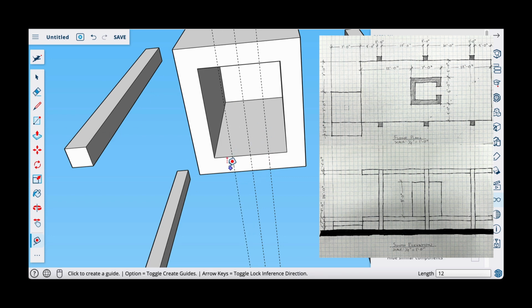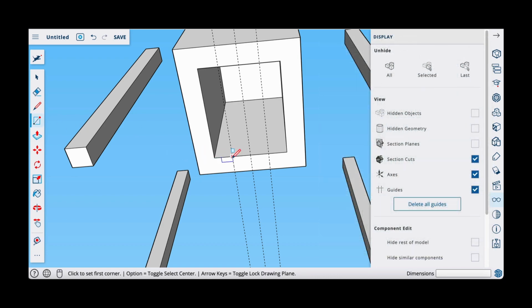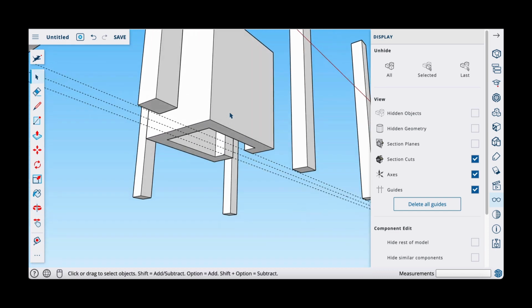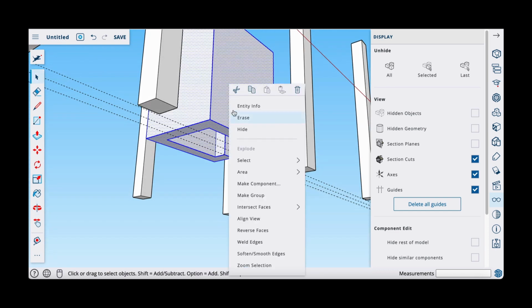Alright, you can draw lines here or use the rectangle to, oops, that didn't land properly. Try that again, Control Z. Alright, and then I'll just simply push pull this up flush with the face of the ceiling here. Okay, and I'll heal this surface to make one face, so I will use my selection tool to select this edge and delete key or backspace to delete it. Alright, so there's that little room. So I'll triple click, right click, make group.